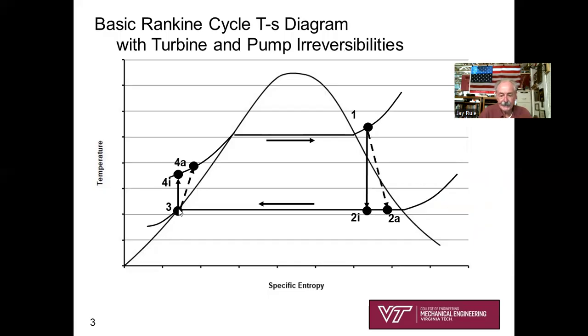We're coming in as saturated liquid into the inlet of the pump, saturated liquid. We're increasing the pressure from P2 up to P1, or in other words, P3 up to P4. Either of those are perfectly good to say, okay? But our job for the feedwater pump is to go from saturated liquid up into the compressed liquid zone, compressed liquid phase. That's an important thing to remember in your mind.